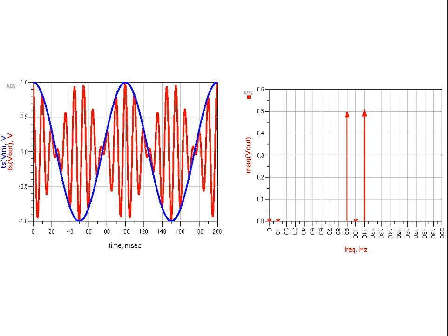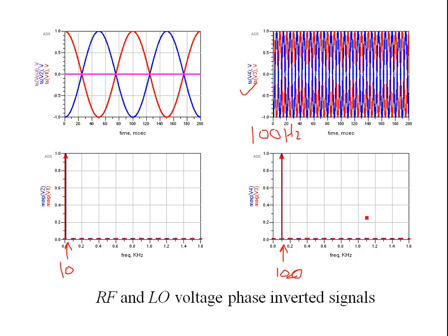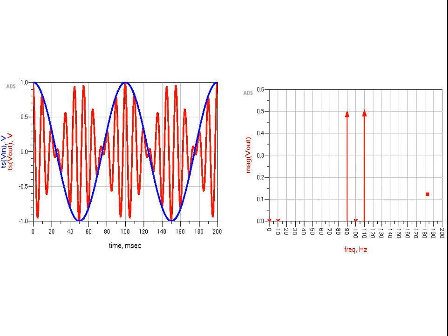So you see that in the spectrum, as expected, the spectrum of 10 hertz, which was like this, this was your baseband signal, is shifted to the carrier or the local oscillator frequency, 100 hertz. So as expected, this is your 100. You see the carrier or the local oscillator is suppressed. You don't have anything at 100. Well, you have the two sidebands at 90 and at 110. So this shows that you have mixed the voltage signals, the RF and the local oscillator signals.